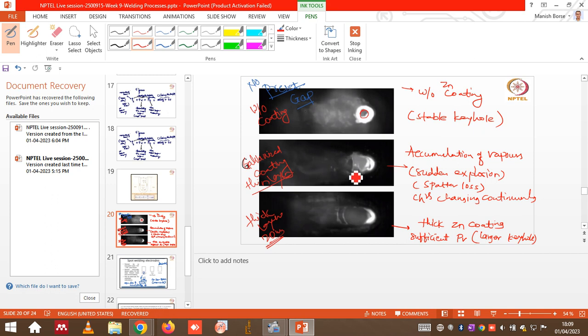But again, as we have seen in resistance welding also, if we maintain a preset gap between the plates and that gap is higher, the preset gap can act as a notch effect, right? In most cases intermetallics are circulated at the center of the nugget zone, and because of the notch effect, the stress will act at the center of the nugget zone and it will fail through the center, because of segregation of the elements.